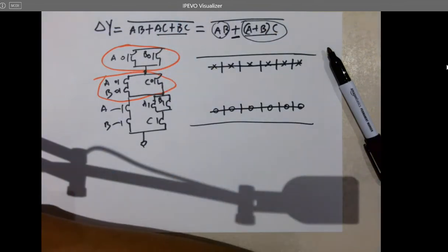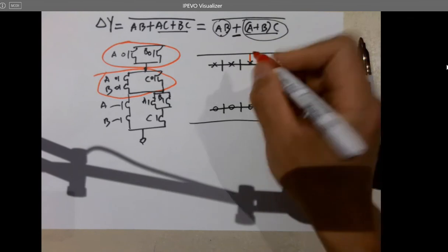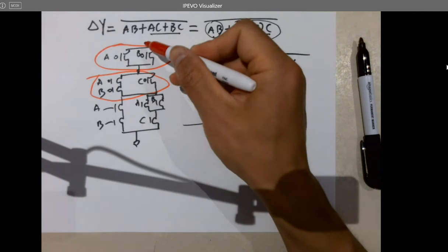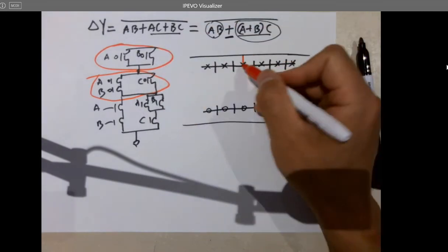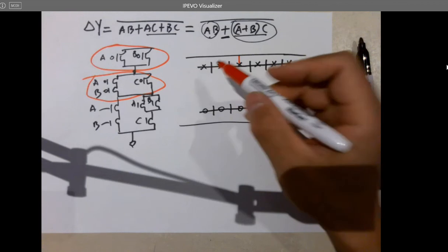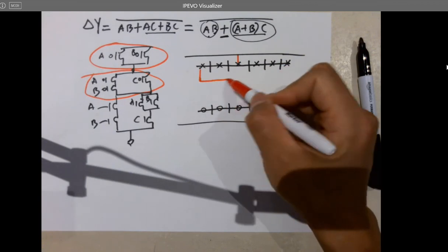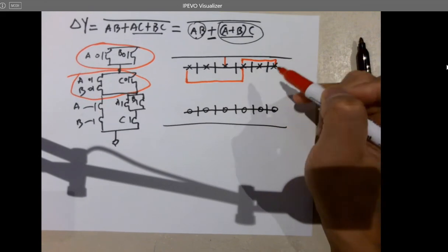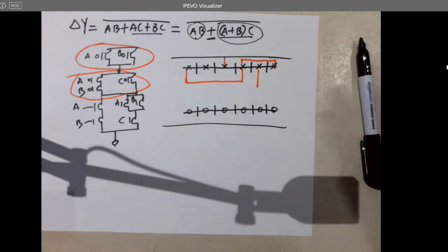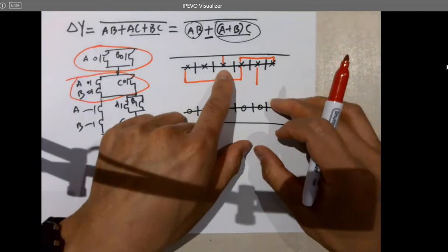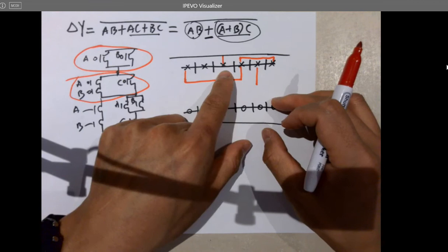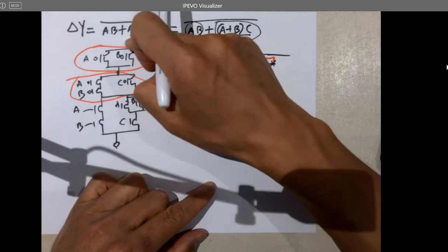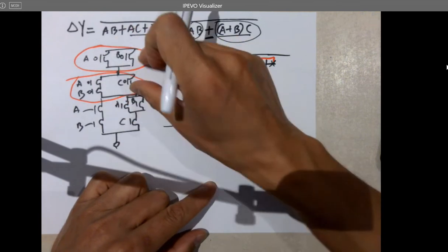And so if I introduce the line here, it's getting A and B. So right now this part is on the top, okay? So it's directly connected to the VDD. So I get A and B here, and then I short this guy to here, and then connect these two together, and that's the output. And now let's see if that's true. This line, so now the circuit has been changed, okay? So this part is on the top, this is at the bottom. I just swapped them, right?